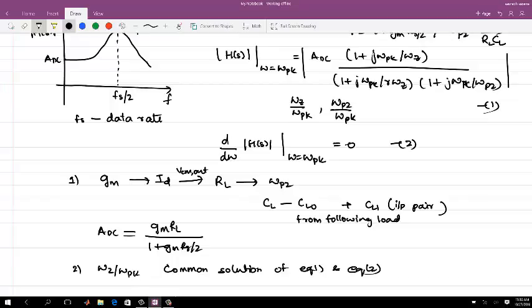You find that, so you get a certain gm value, you find omega Z by omega peak in this particular manner, and you do this like maybe a scripted simulation, that you do this process and find the minimum value of gm for which you can satisfy all of these, because that will be the most power efficient design, which gives you all the parameters required.